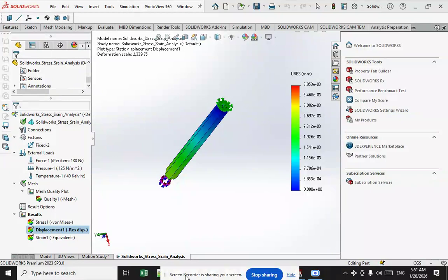For a perfectly elastic solid, the resulting strain and the stress will be perfectly in phase. For a purely viscous fluid, there will be a 90-degree phase lag of strain with respect to stress. Viscoelastic polymers have characteristics in between, where some phase lag will occur during the DMA test, or dynamic mechanical analysis test.